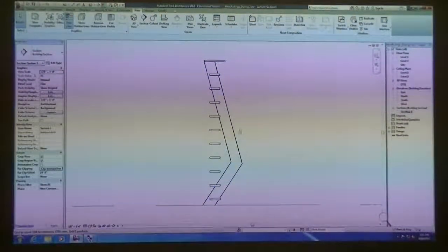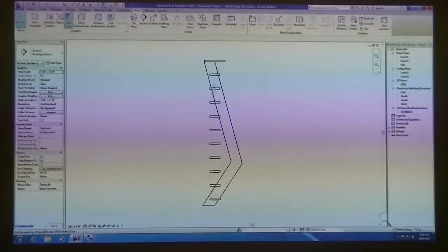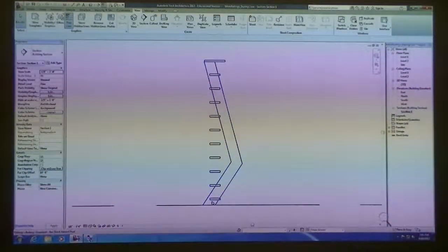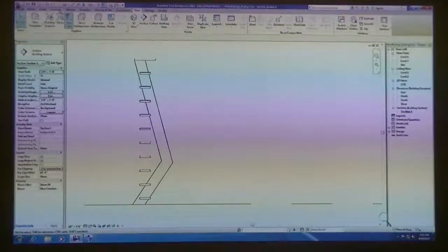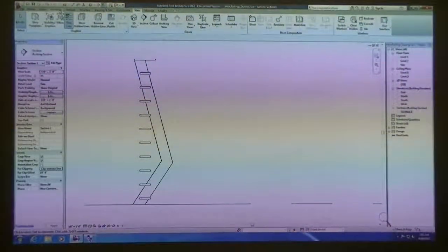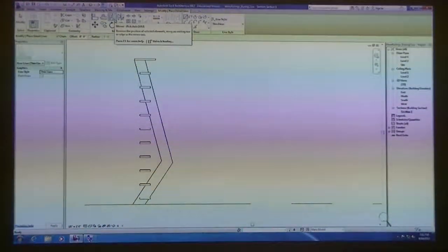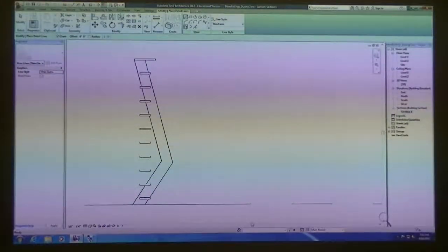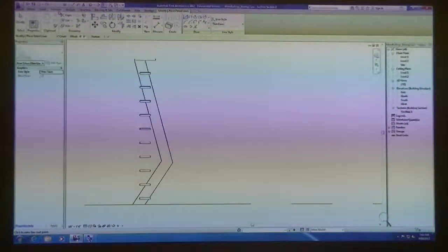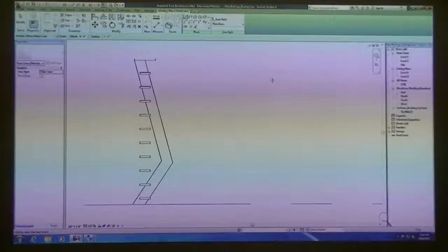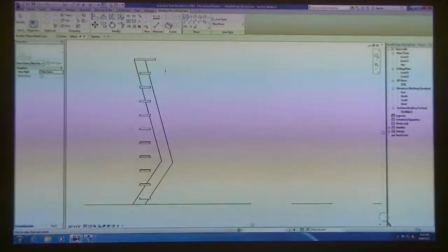And I'm going to look at my railing system now. You can see I've got it where I've got all the profiles directly lined up, and now we have to figure out how far we have to offset all of these. Well, this is where we need to start to sketch a little bit within Revit. I do a lot of sketching with annotation and detail lines, because these are just lines that are particular to this view, and they're something that we can easily erase later, and they don't affect anything in the model. Annotation lines are like drawing on a piece of paper over this particular model or this drawing. We're just drawing these drafted pencil lines.